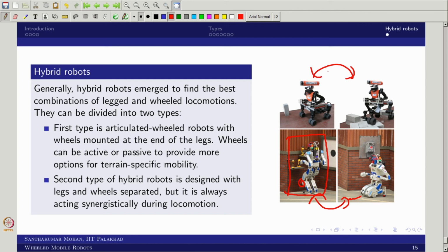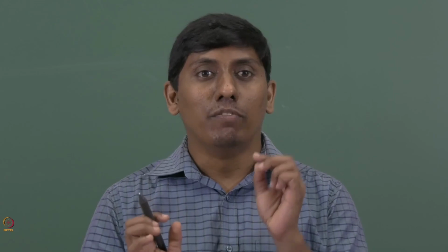Now you have seen what a legged robot is, what static equilibrium is and how to achieve it, and you have come across two points: the center of mass, and the center of pressure, or as we also call it, the zero moment point. At the end we have seen what a hybrid robot is. Now we have started touching topics which are not covered in the main lecture. I am just giving a lecture introduction, so you can explore yourself.